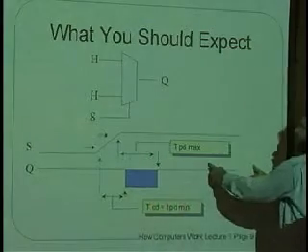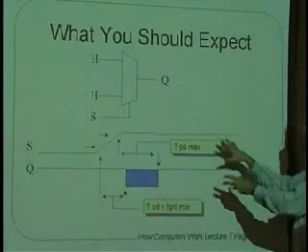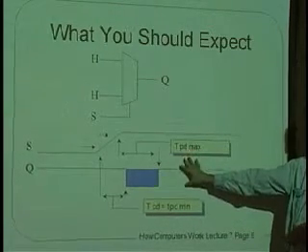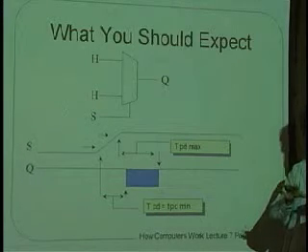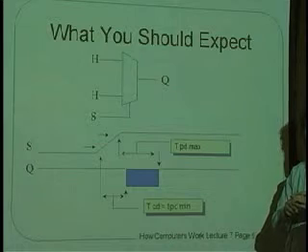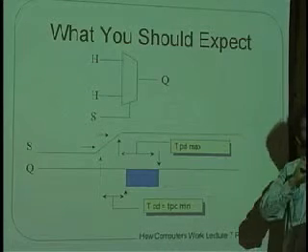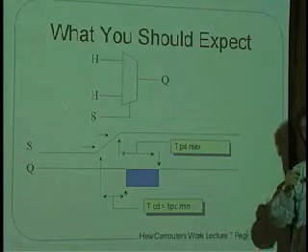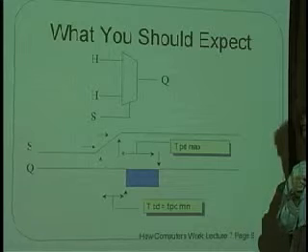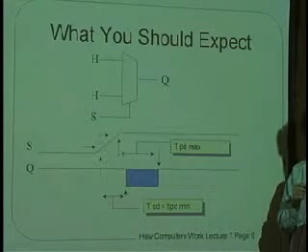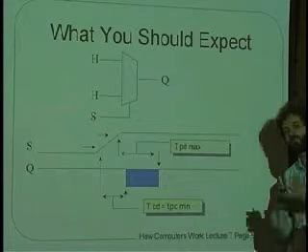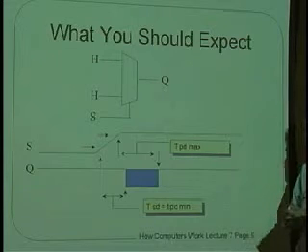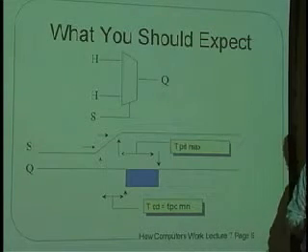There is no relationship in this picture here that says TPD max is more than TPD min. Nothing in this picture proves that. I'm telling you that in general, TPD max is bigger than TPD min. Could max be less than TPD min? Because we've inserted this difference between valid and invalid, according to that definition, one could imagine a circuit in which that were true. In truth, there are no circuits like that. But from what you know so far, there's no reason to believe that the max should be bigger than the min. Except that it is. And you'll see why later.